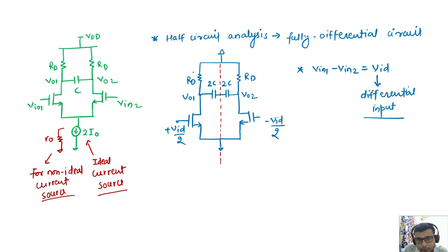So this circuit can be divided from the middle, because the C can be written as 2C and this midpoint can also be a virtual short. So the thing that we can conclude here is that this point is also a virtual short, and this point is also a virtual short. So I can write the half circuit in two ways. How can I write the half circuit?